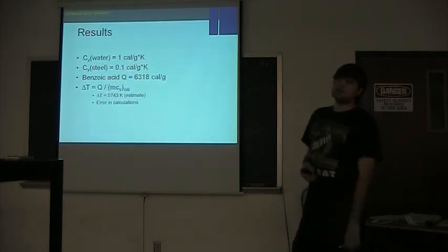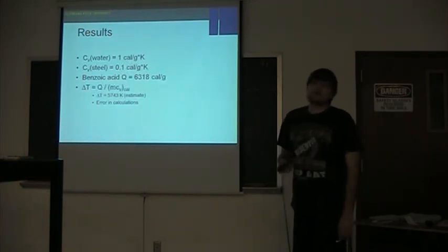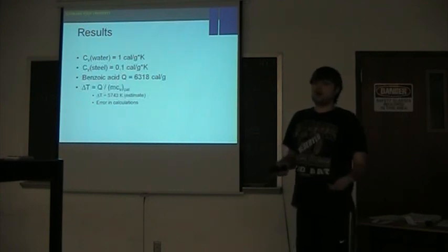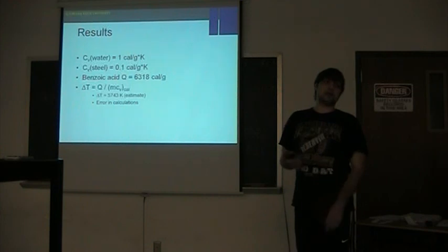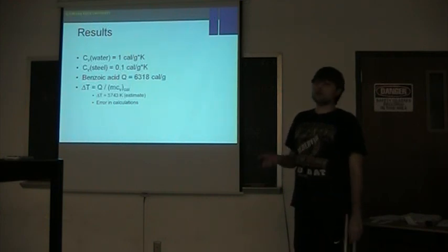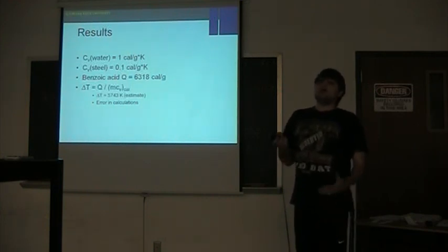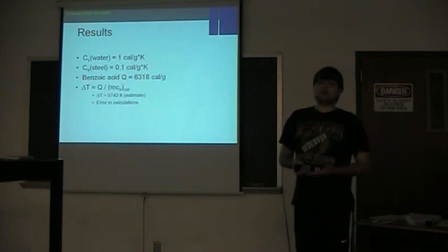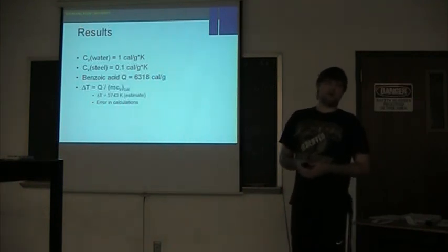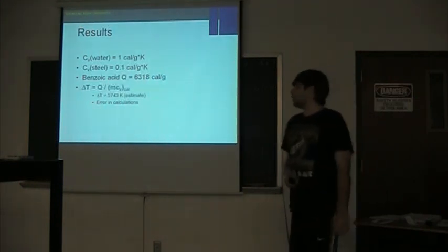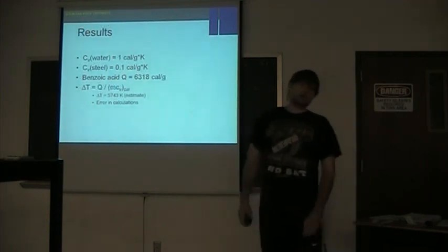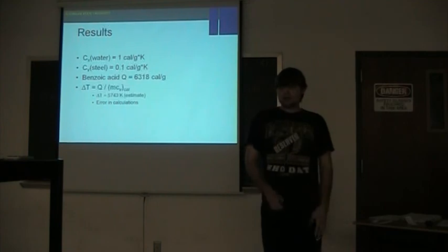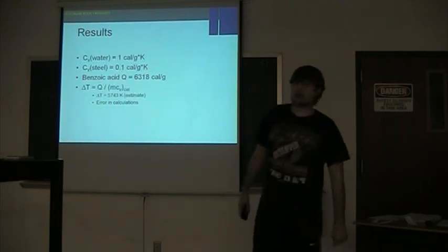Uncertainty in this experiment is anything, basically human errors, obviously, as in any experiment. Uncertainty in your type K thermocouple, as well as any uncertainties in the measurements of fuel that you use to burn and the amount of water. If you mess up on any of those, your calculations could be a little bit off. Are there any questions? All right, thank you.